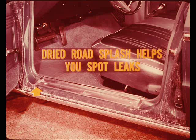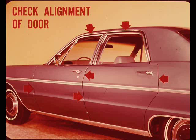So let's go back to weather strips. Sometimes after a rainstorm, the dried road splash around the door opening surface helps you to spot leaks. If the weather strip lets in water, it can also let air in or out. And while you're looking, check the alignment of the door in the body opening and also note whether it is flush with the adjacent body surfaces.